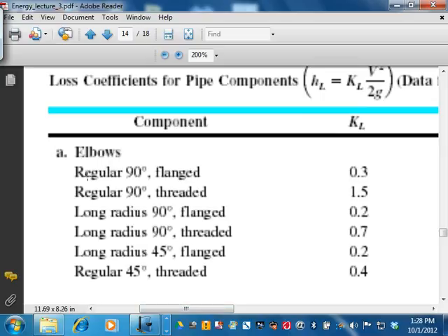For the pipe, settle down please. For the pipe connection, there are two types. For your half-inch pipe, they tend to use the threaded connection where you can screw the pipe pieces together. You played with that before, no? You can screw. For high pressure application, that doesn't work. You put the plumber's tape and then you screw. That's okay for small pipes and for low pressure application. But imagine trying to screw pipes as big as this. Where do you get a spanner so big? So for big pipes and for high pressure applications, the threaded screw joints would not work.